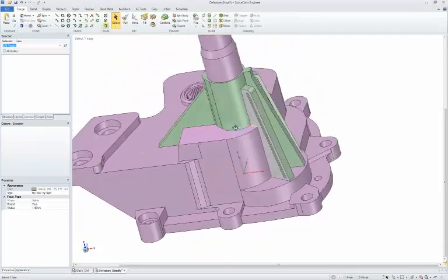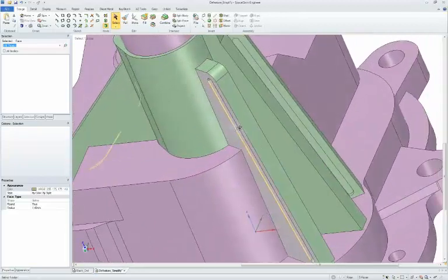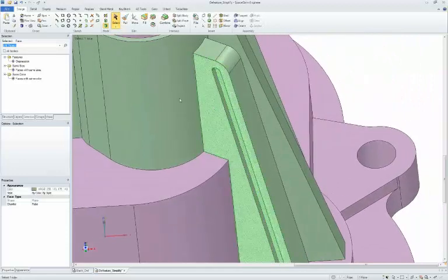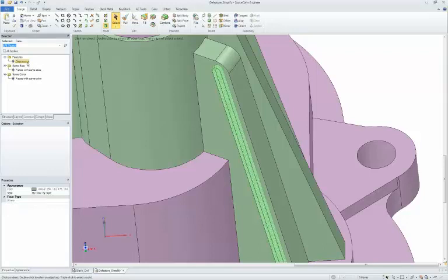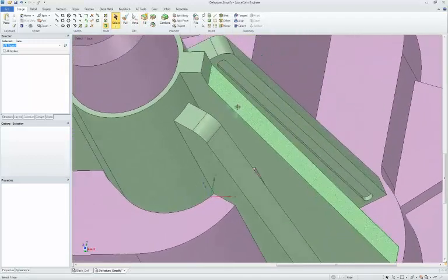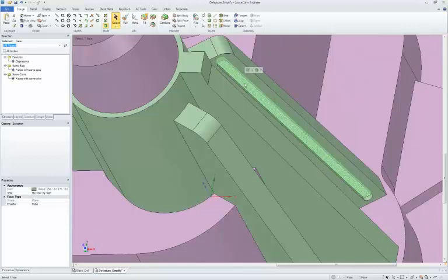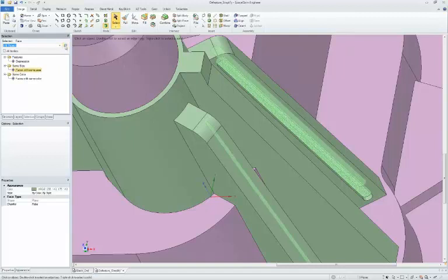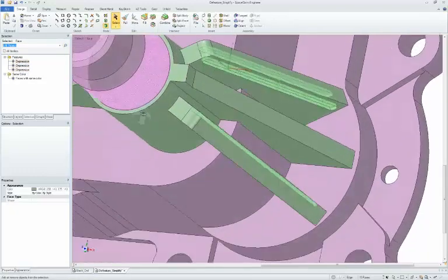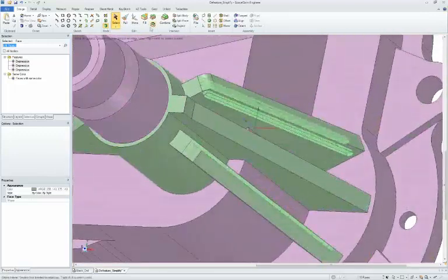But what I want to do is also point out that, again, for things to remove, it's up to you. These might be small, thin faces that aren't adding much to your analysis. That's the type of thing that I like to search for, find, and destroy with fill. And the whole thing with searching to remove these types of features is it's fast to fill, fast to select, but you can make your life a lot easier by even speeding that up, kind of putting a turbocharger to it, by searching for things of the same area, things of the same size. So instead of removing one depression at a time, you can find all of these similar depressions on the model and get rid of them together.